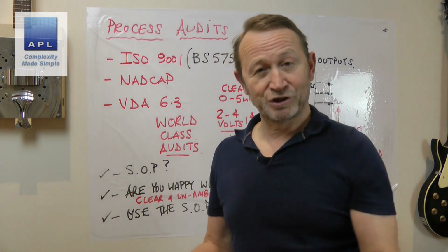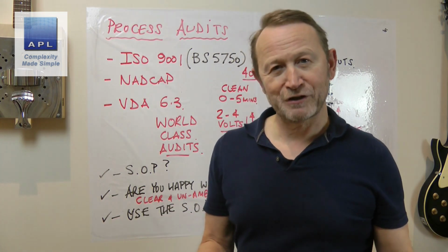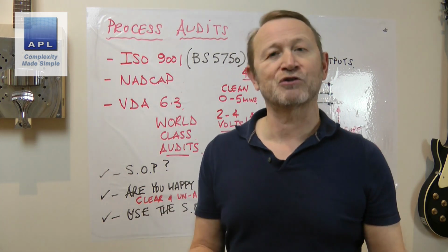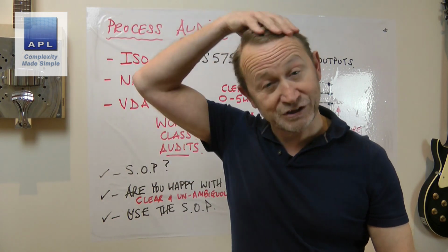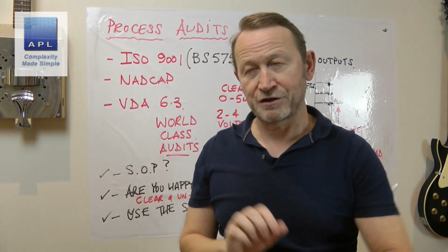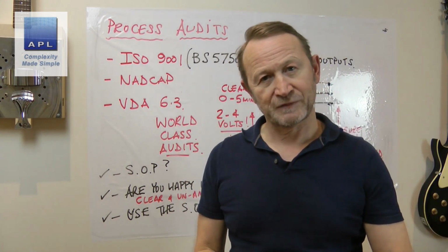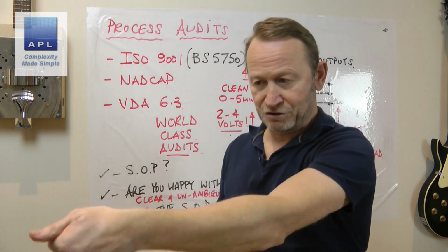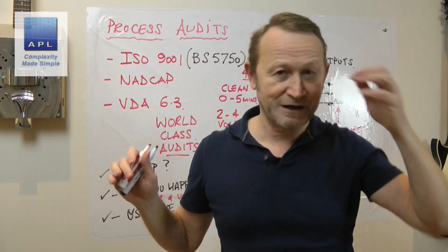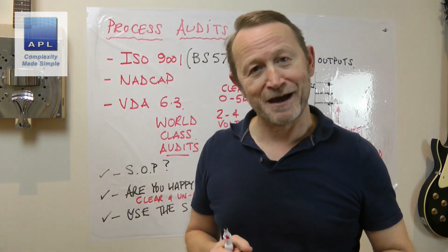Oh, you can choose. Now, electroplating, it's based on physics. You can work out the voltage that you need depending upon the surface area that you're trying to plate. It's a calculation and there is a correct voltage to be used. The operator should not have choice here. They should be told to dial it to a value. Once they've dialed it to a value, take their hands off. It's not going to move. The volts are going to be there.